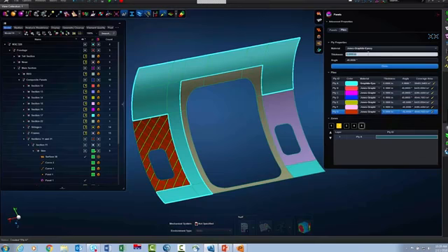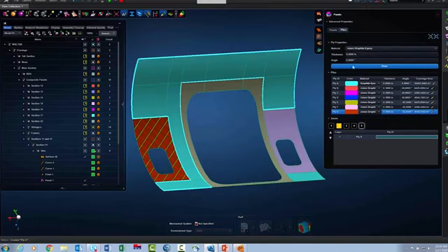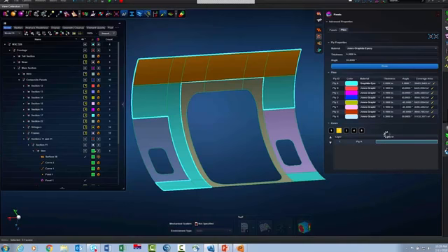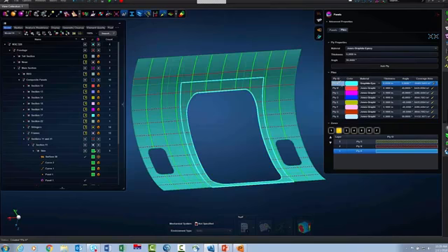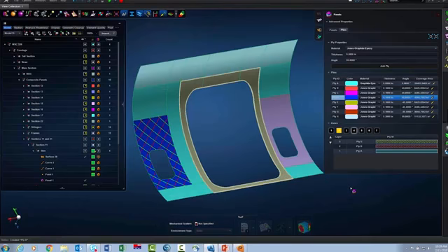And now let's add one more ply. And once again, I'm not advertising that you want to fly in my airplane. So we're going to add a 90-degree ply up here at the top, okay? So we'll add this ply up at the top, selecting those surfaces. And when I add that, once again, Apex is automatically making some additional zones for me. And at any time, I can review where these plies are, and I can review what the contents of the zones are if I need to.